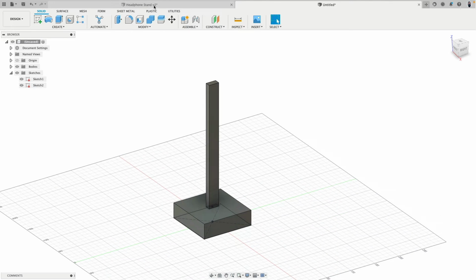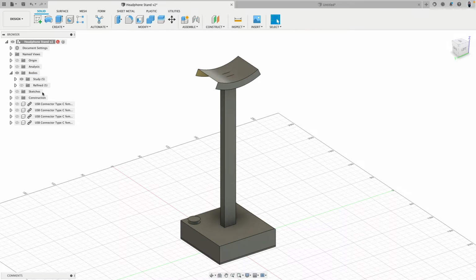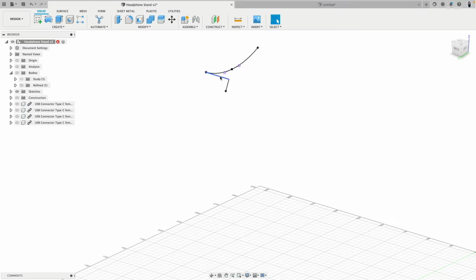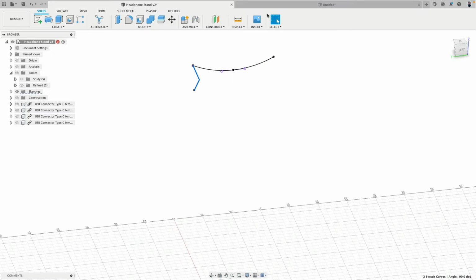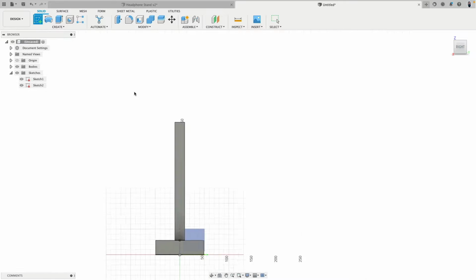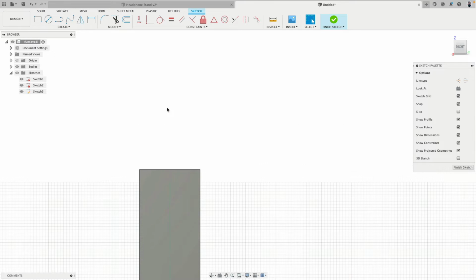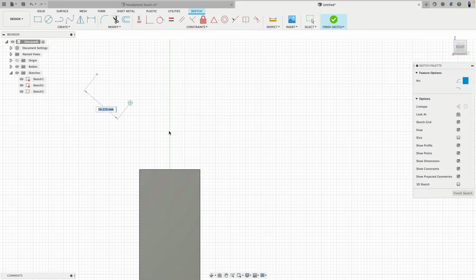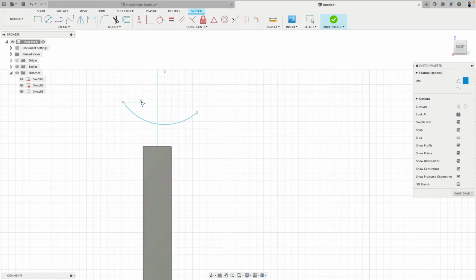Okay. So how do we do this part? That's actually quite easy. See, this is all what we need: an arc and kind of like a track. I go to the side view. Then on the side view, I create a sketch. And this should be an arc, click, click. I click those on purpose a little bit off, so I can explain everything we have here now. Left point, right point, arc, center point.